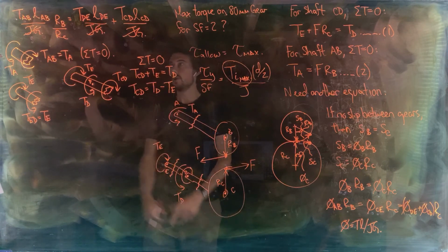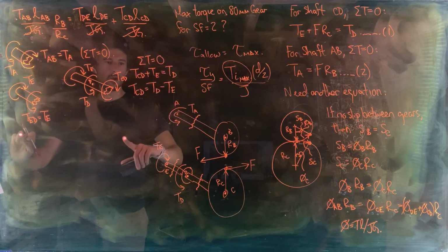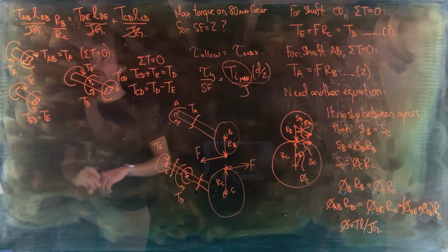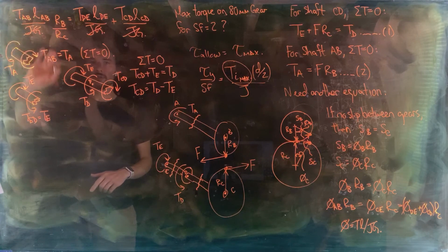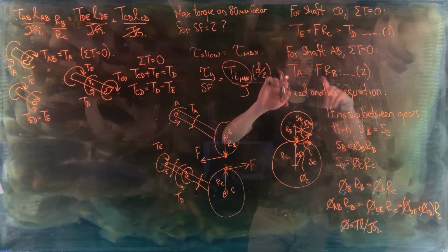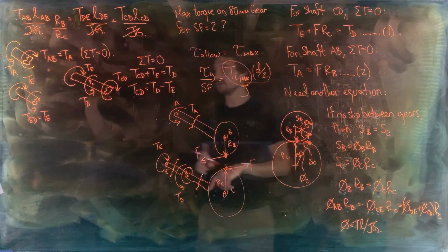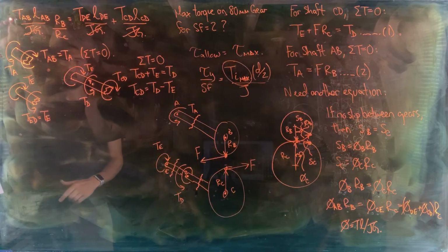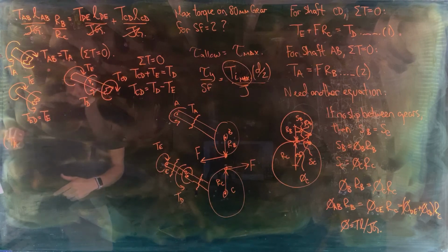There we go. So now we've got an expression for the internal torque TCD. Okay, so we can continue with this equation up here down on this next line below those free body diagrams now. So let's substitute in for the internal torques in terms of the support reactions, and then we could get another equation that would have the support reaction torques in that we could solve with these two equations involving the support reactions that we've already got. So TAB is TA.